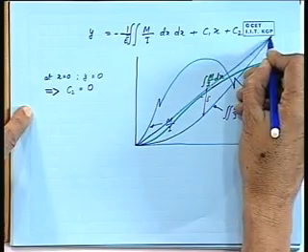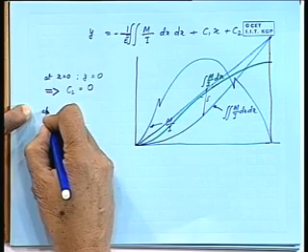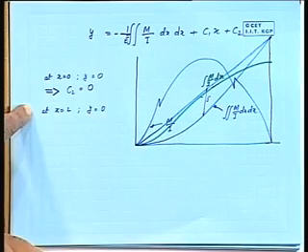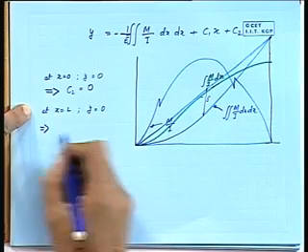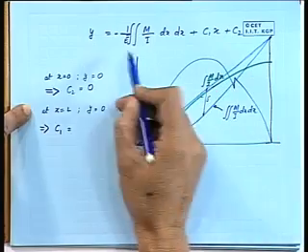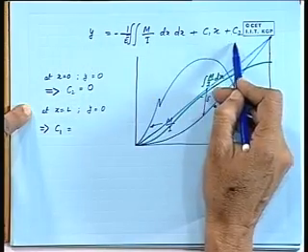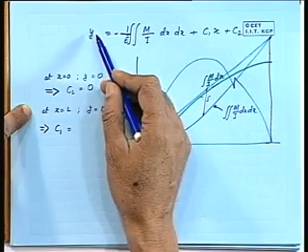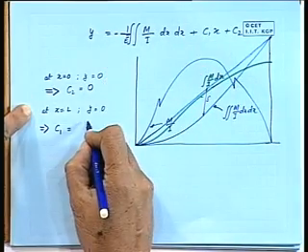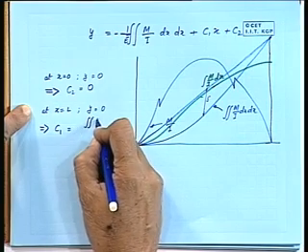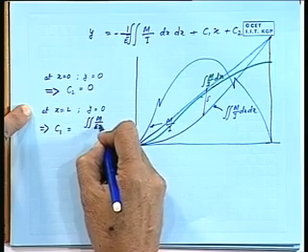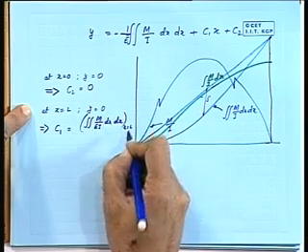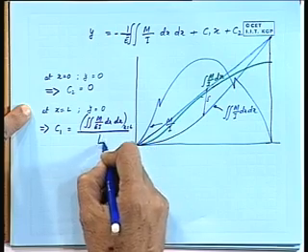And then when you come to this particular point, we have the condition at x is equal to L, once again y is equal to 0, and this leads to, after putting the value, this is 0, this is already 0 here. So, what we get is C1 into L is equal to this integration. Okay. So, from there C1 is equal to minus, I will put EI here itself, double integration at x is equal to L divided by L.